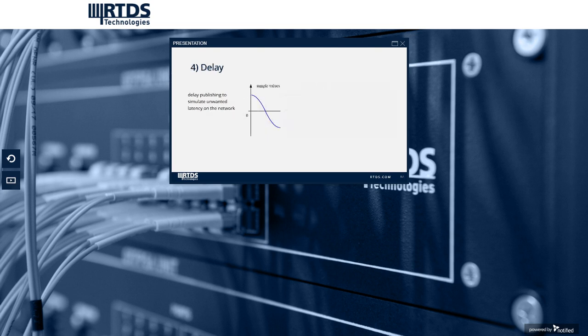The fourth one is delay, which is pretty common. It is to simulate unwanted latency on the network. The last is jitter. Jitter is the variation of latency. It happens all the time in the network. We are able to add positive or negative jitter to the SV streams. We are able to control the jitter in the resolution of 10 nanoseconds, which is very accurate. This is due to the FPGA design, which can have very good control of timing and clocks.